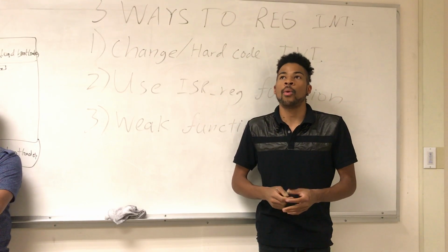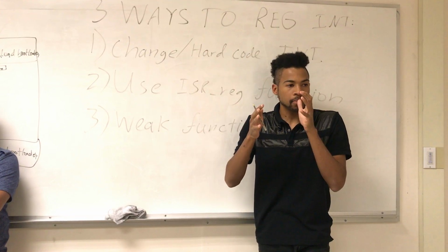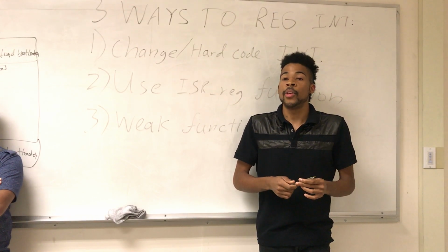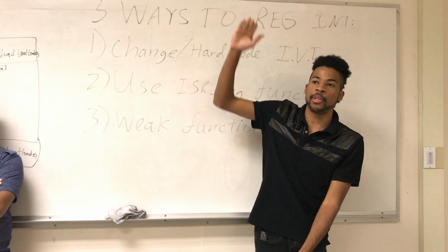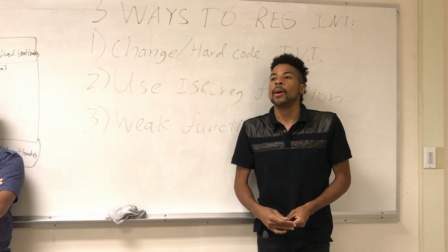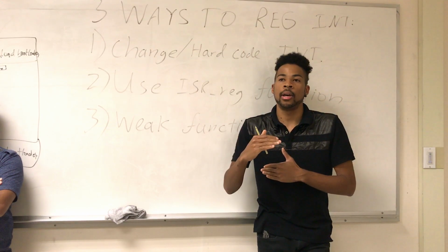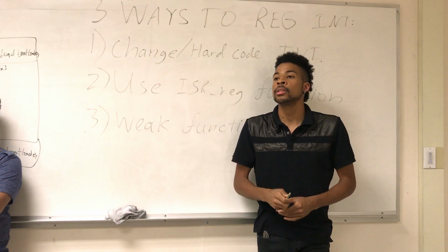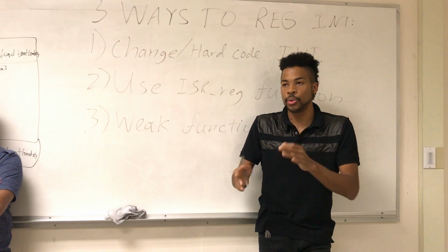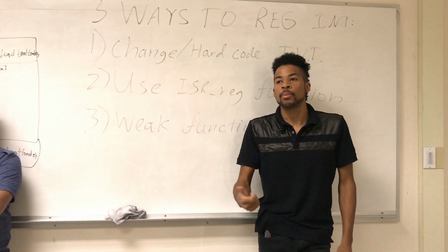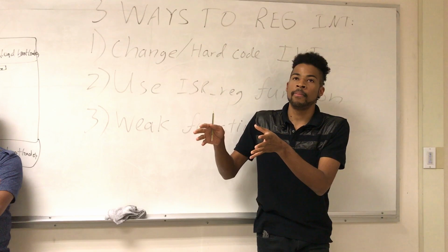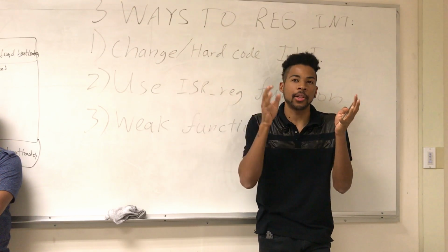I wrote the handler that will assign a particular either rising or falling edge interrupt to a particular pin in about 6 lines. The other alternative is to just use a big old list of if statements for all 64 pins. Obviously that might be a little ridiculous, correct? So the idea is to write your own interrupt controller class, and to be able to take in any arbitrary port, either 0 or 2, and a pin number, making sure that it's valid, and then a function call basically, and assign that to a particular pin.